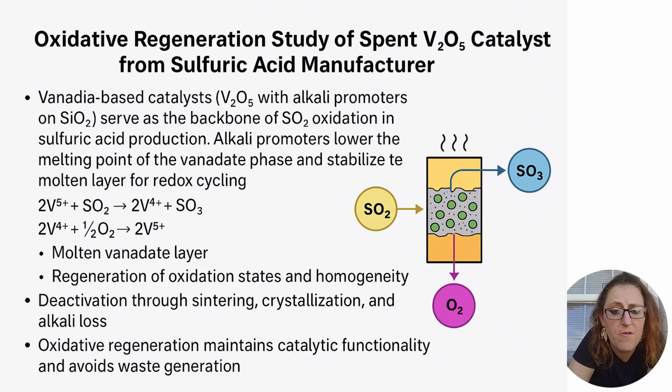High P_SO2, the partial pressure of SO2, can cause surface poisoning by excessive SO2 absorption, while excessive oxygen can shift the equilibrium toward inactive crystalline phases. A practical implication is that the reactor design must maintain intermediate oxygen partial pressure and uniform temperature distribution to avoid